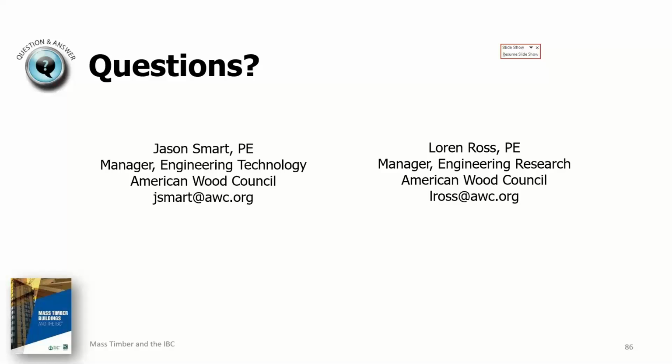So that's what would need to be specified, and just reference that section of the NDS, and state the fire resistance rating requirement. And also, we do encourage folks, have a conversation with your glulam supplier if you're not sure. It doesn't hurt to pick up the phone and talk to the folks that are manufacturing it and tell them what you need, just to get everyone on the same page.